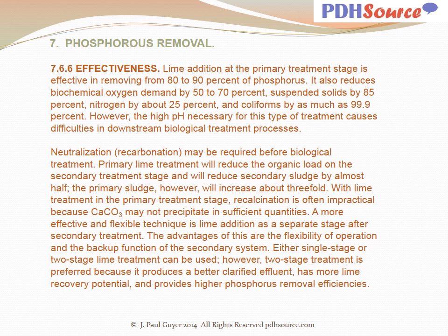With lime treatment in the primary treatment stage, recalcination is often impractical because calcium carbonate may not precipitate in sufficient quantities. A more effective and flexible technique is lime addition as a separate stage after secondary treatment. The advantages of this are the flexibility of operation and the backup function of the secondary system.